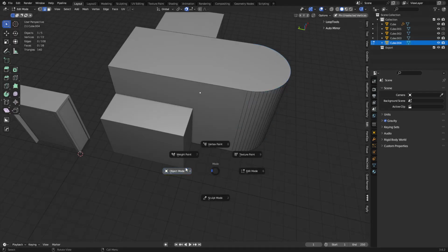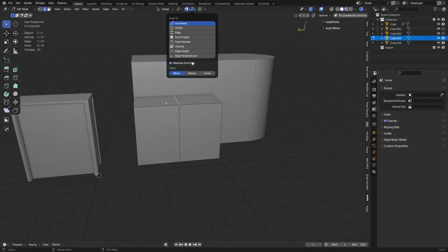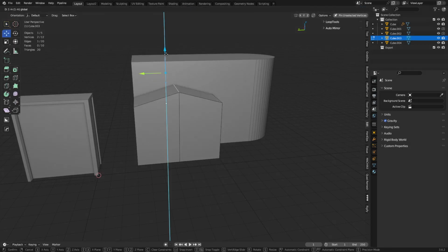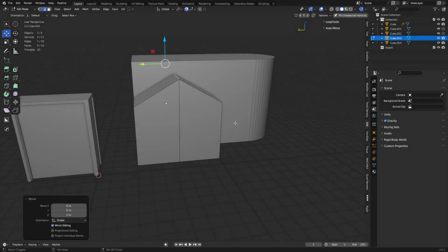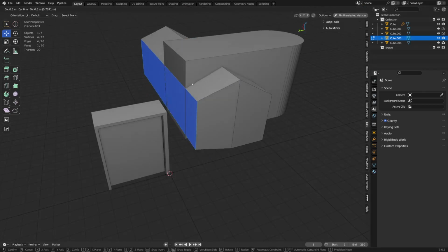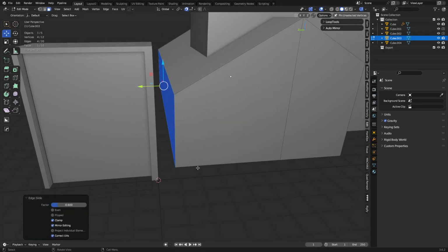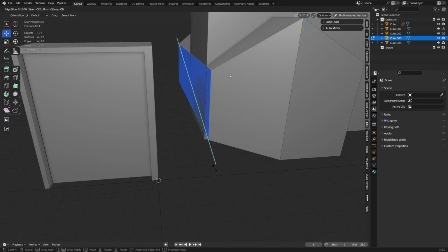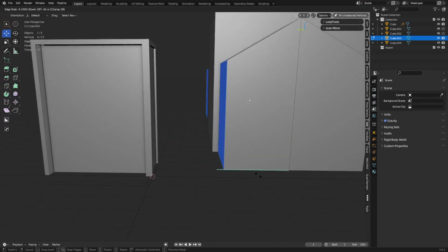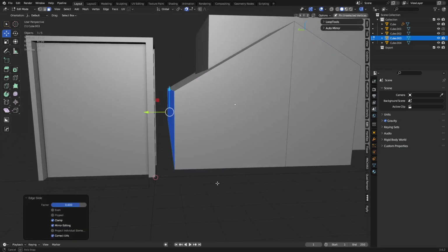All right. If you want to ever create like a ceiling section, turn absolute grid snapping on, right? And so if you were to move that up, you can snap it to every meter, whatever the case there. Some of these edges are interesting because you can actually GG twice and slide them back and then hold Alt and then slide them back forward if you wanted to extend things a little bit. I don't think these snap necessarily to the grid. Yeah, you see, it doesn't really snap to the grid though. So it's a little bit weird. Oh, maybe it does. Maybe I just missed it. I don't know. It's close, but it's not quite there.